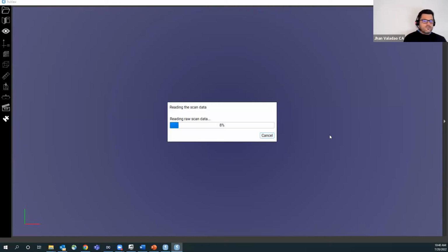So say you're scanning with an RTC and you've scanned about 50 scans on the job site, but there's just one area that you need to validate right there and then. Pulling out the memory chip from the RTC and then dropping it in the project folder allows you to select only one station. You don't have to go back to the office. You don't have to register. You don't have to do any alignment or any editing. You are just taking that one single scan and dropping it into your laptop in the field.